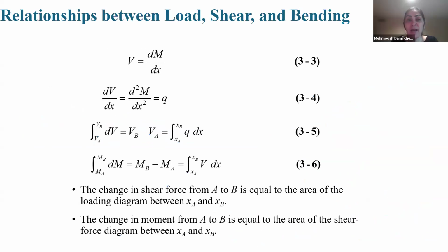We had this in the last video too, but maybe you didn't know the relations and their importance so much. Today, we want to talk about them in detail. Here is the key relationship that you will use in every beam problem. The rate of change of the shear with respect to X equals Q, meaning dV/dx is Q, or vice versa, dV equals Q dx.